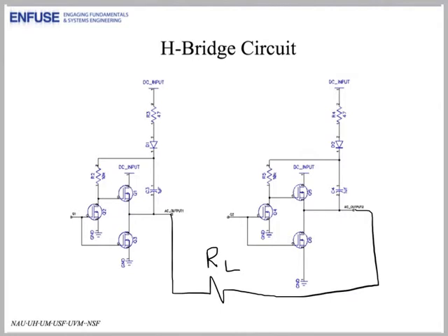Something is different here. Why are there 3 MOSFETs for each parallel branch of the H-bridge when previously we have always considered 2? This is described a bit more in the laboratory procedure, but notice first that the Q1 signal from the first flip-flop arrives here, and the Q2 signal from the second flip-flop arrives here.